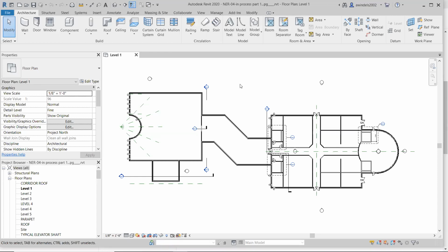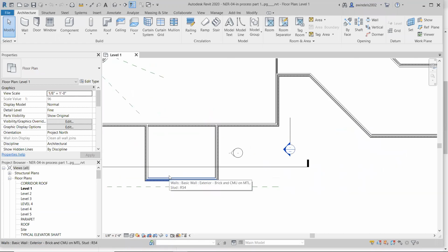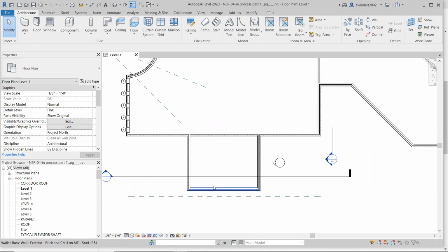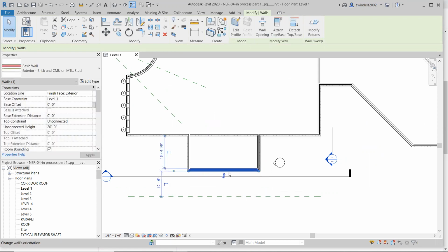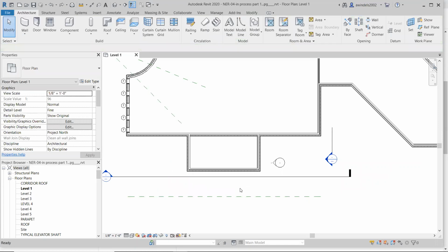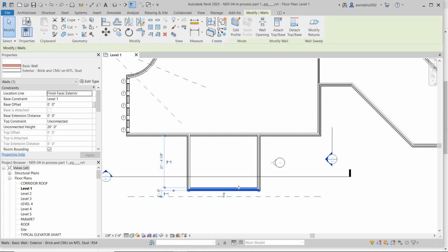And we're going to go to the west wing over here, and we're going to take a look at this wall, different ways to move it. So we're all familiar with the orientation of the wall. You can flip which side's exterior, interior. You can also drag and hold because my move command's on, and things are constrained and joined. We'll move with it, right?